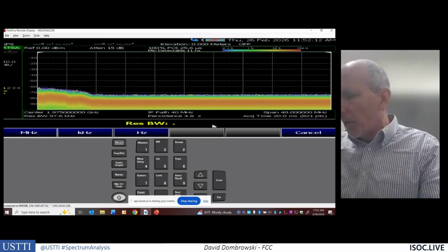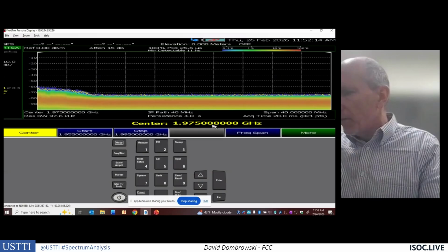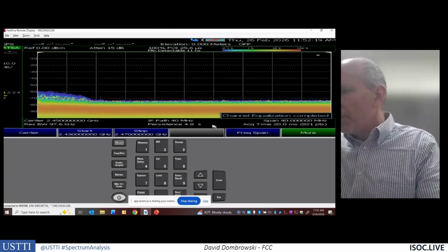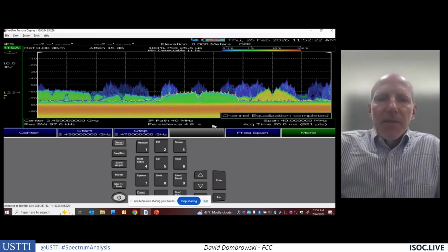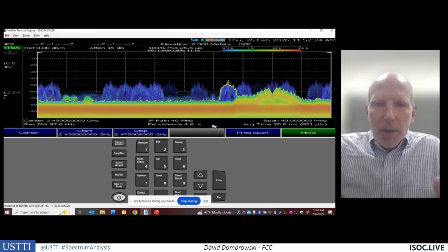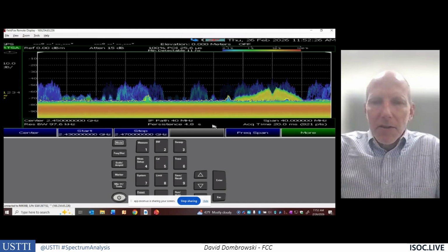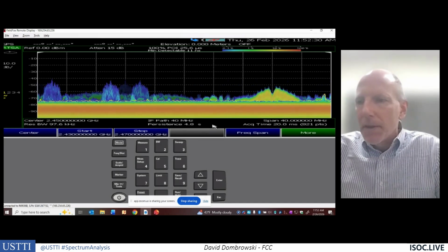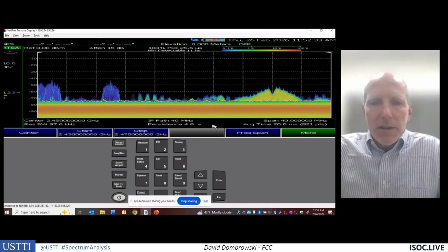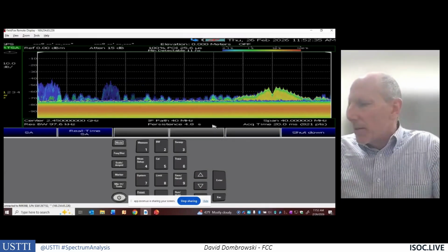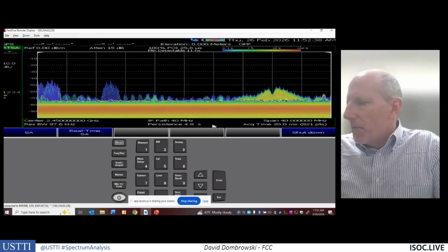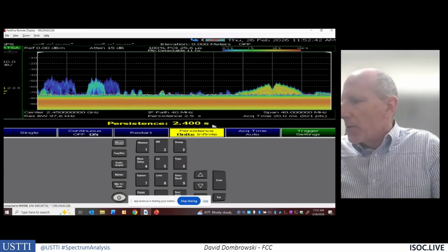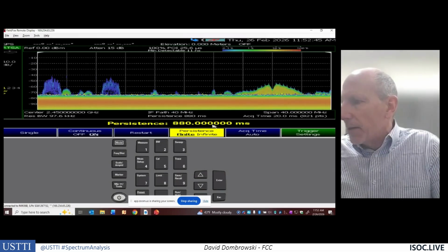And if I go to the 2.45 gigahertz band. All right. This is the Wi-Fi band. Bluetooth, Wi-Fi signals here just in the office. Probably my Wi-Fi routers are working in here. My cell phones are on the Bluetooth connection. And we see these signals. With persistence, in the real-time mode, I can change how those signals appear on the display.